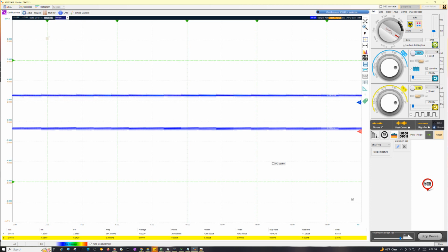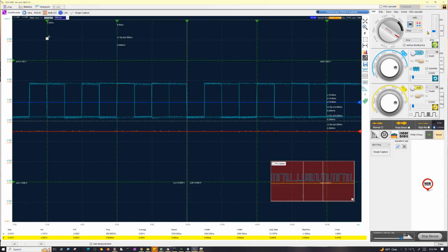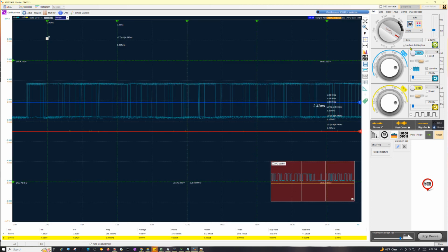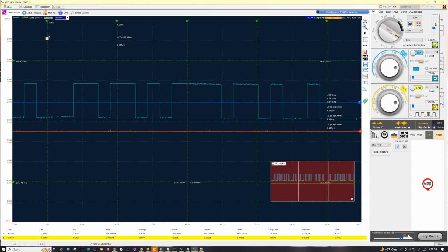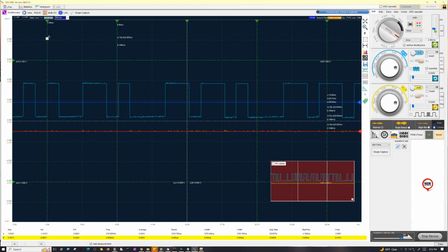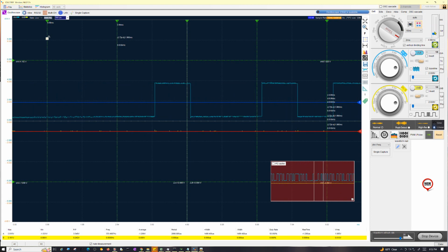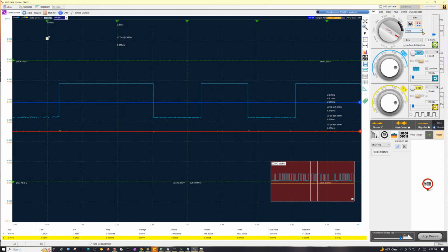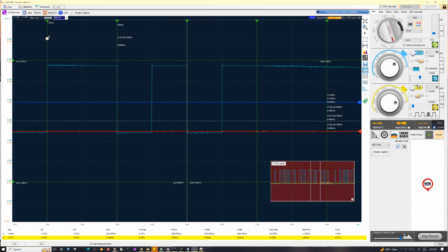But anyway, that pretty much covers it all. So, good enough. You've got these sliders, which are for zooming in on things, and it gets kind of confusing, this whole timing thing of theirs. Here, let me turn this persist mode off. But you can control the time scale in fine increments, which is kind of nice, because older oscilloscopes used to do that. Most of the digital ones these days, I don't think, do. I still don't really know what this box is for. You do have an automatic measurement setting, so it'll try to figure out a good voltage and frequency setting for you.